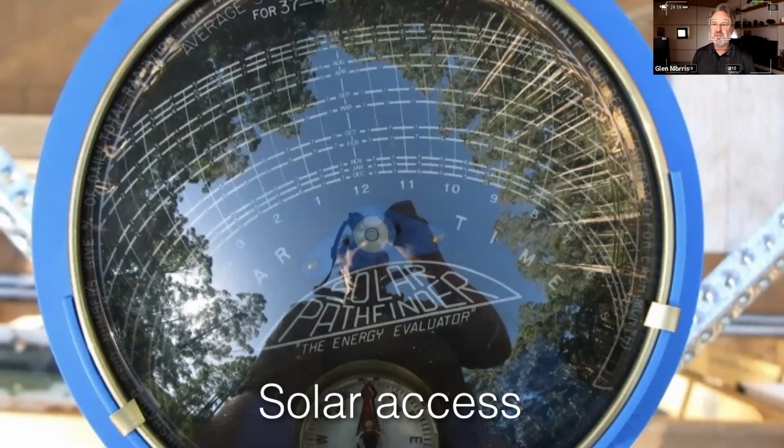Those percentages can be summed. So if you know what the sum of the shading is, or the sum of the unshaded, you can then use that as a factor for derating the theoretical peak sun hours for that particular surface to the actual peak sun hours based on a seasonal or monthly figure. So it's very useful for doing quite detailed calculations.